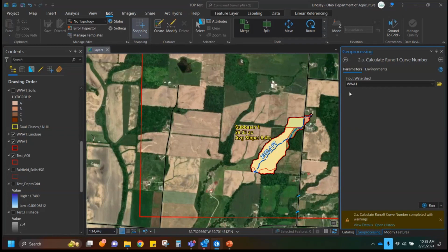And then there was a question that says you still need to correct the hydro group from 2-lettered to 1, but I think you addressed that, the C/D. Yes. It will not run properly if you do not select those. It won't be able to select the correct runoff curve number on the last step.